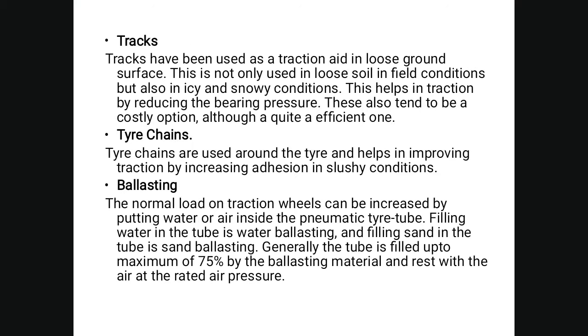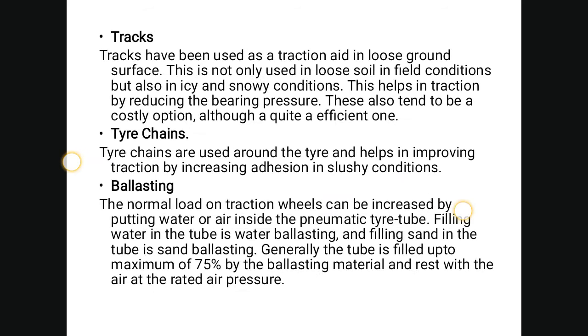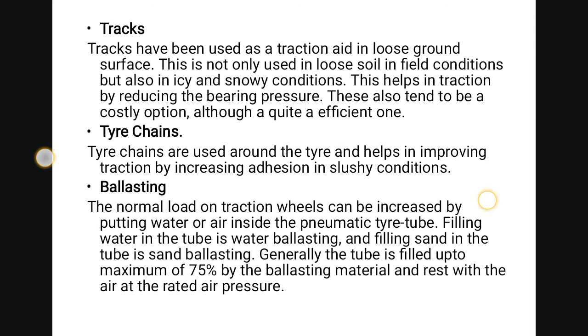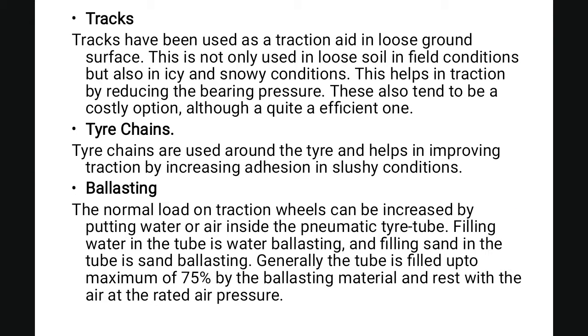Now tracks have been used as a traction aid on loose ground surfaces. They are used not only in loose soil in field conditions but also in icy and snowy conditions. This helps traction by reducing the bearing pressure, and tracks also tend to be a costly option, although quite an efficient one. Now tire chains are used around the tires and help in improving traction by increasing the adhesion in slushy conditions.